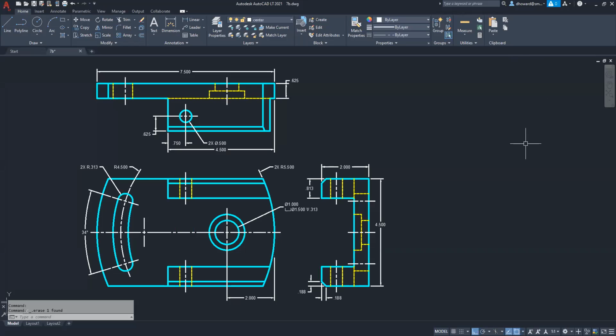All right, so we are going to create the isometric view of the Clappervox. We have done the 3-view drawings for it already. So the next step is to come down to our toolbar on the bottom, click on the little arrow next to that array of dots, which is the snap mode, and then click snap settings.